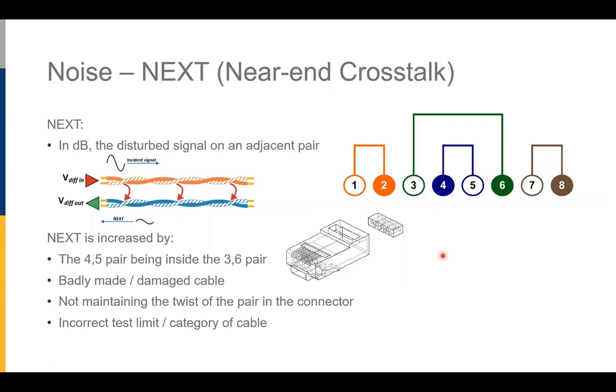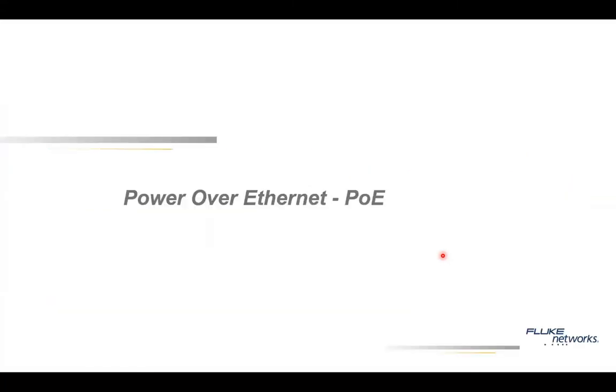And there's another reason for us to do the test. Boxes of cable are not generic. They do not say in giant letters what they are. They say in giant letters who made them. But you've got to get into the fine print to see: is it 4-pair cable? Is it category 5? Or is it category 6? And somebody might just accidentally install the wrong cable. If we certify it, we'll catch that.